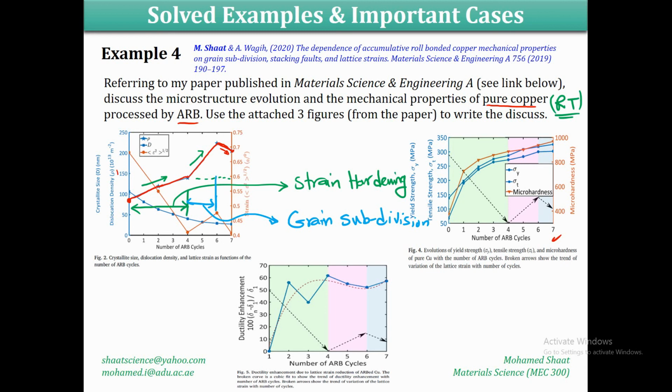and this indicates a recovery. We said that recovery is one of the annealing processes, and if you recall from the previous video, we said that recovery does not necessarily require heating the material. The recovery could usually be done without heating the material, and this is what we observe here. The dislocation density indicated a recovery of the material. To prove this, we observed a decrease in the lattice strain. So we have a third range, and within this third region, we have a recovery.